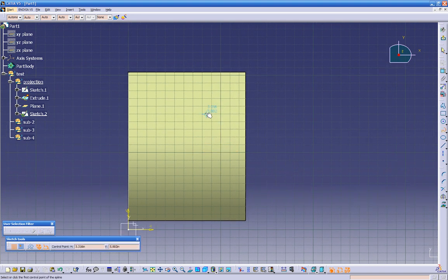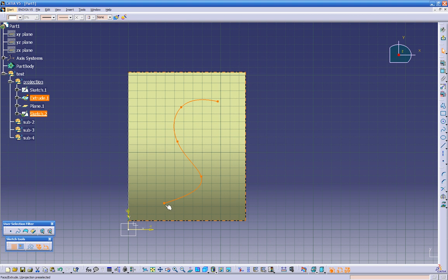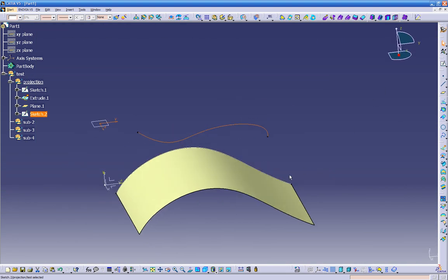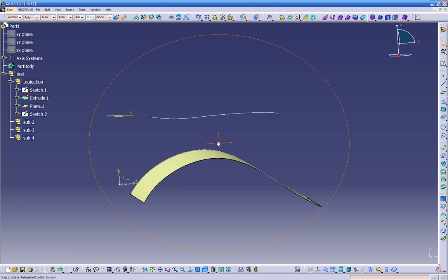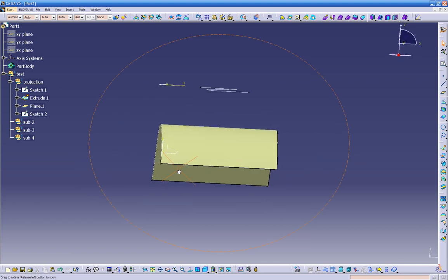And let's create another spline. Let's hit escape now. As you realize right now, the moment I move it, it gets weird shapes. But when I hit escape, this is going to be my last point right here. So even though my shape looks pretty weird right now, this point right here is going to be my last point. So that was our last point right there. So let's get out of this sketch right now, and let's give it one more sketch into this view.